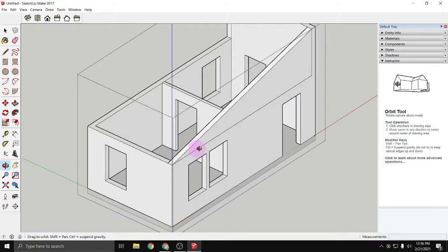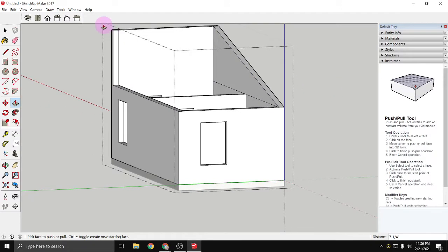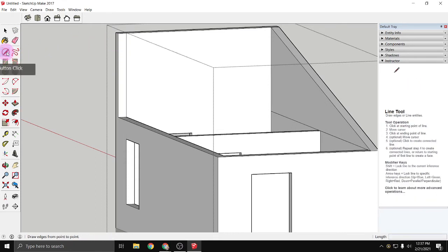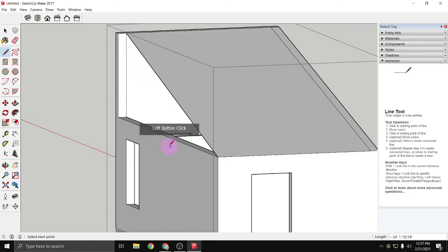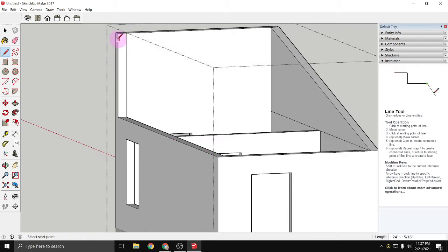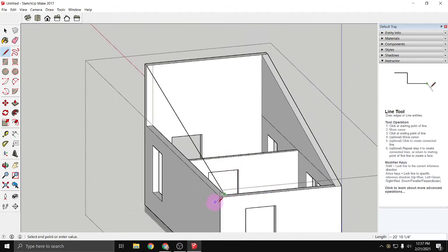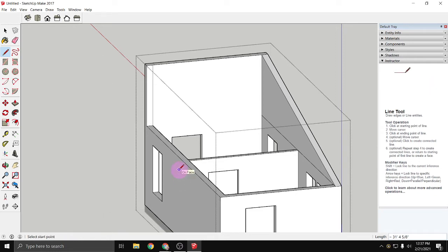One thing too, when you're drawing from endpoint to endpoint, you want to always double check that you are drawing from the right ones. So for example, I could accidentally start on this face to this one, and now I'm getting a weird wonky shape. Or I could go from this face to this one, and then I'm like, well, why didn't it fill in? And then what I tend to find is students just keep clicking, clicking, clicking until it looks like it's right. And then further down the line, they realize that there's something within the model that's just compromised and weird and wonky.